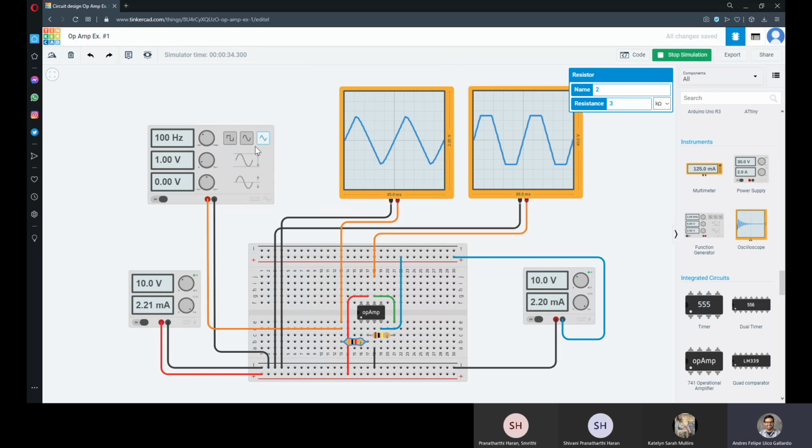Well, actually, that's a volt peak to peak. So that will be like half a volt times 33. That will be about 16. But we know that the maximum output of my power supply is 10. So we see this cropping, saturation both at the top and the bottom.